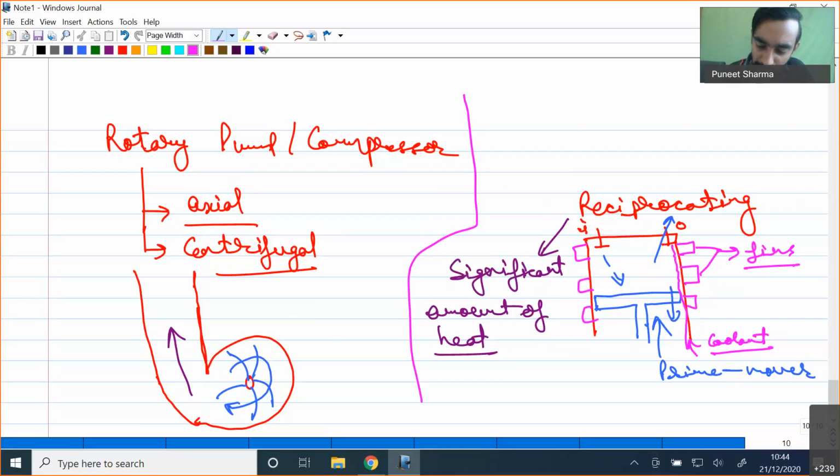You will find more details about these compressors in later subjects like fluid machinery, but for now, if no condition is given about heat transfer, consider the process inside the compressor to be adiabatic.